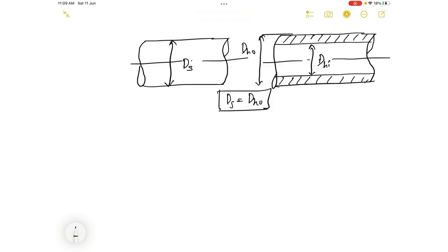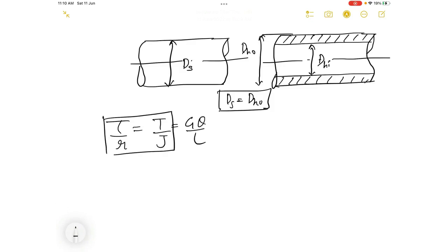So what I have to do is, first I need to find the torsional shear stress for both of these shafts. So we need to find an expression for the torsional shear stress which comes from the torsion equation. So I'll just write the torsion equation, which is tau by r, T by J, and G theta by L. So I'm going to equate these two things.